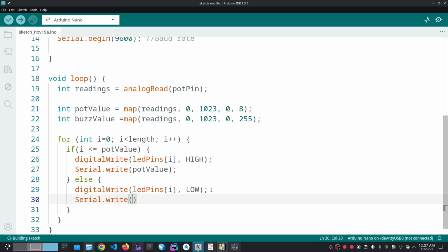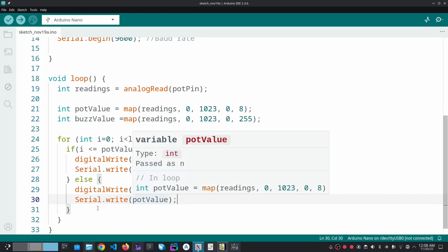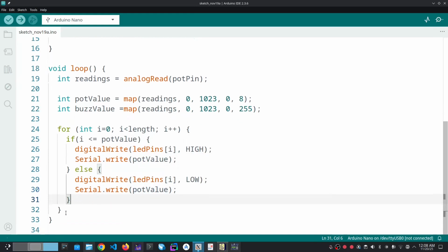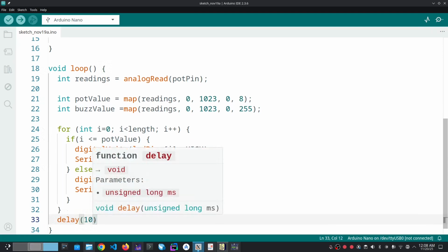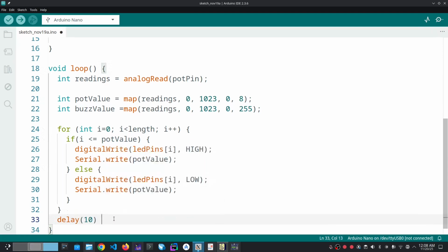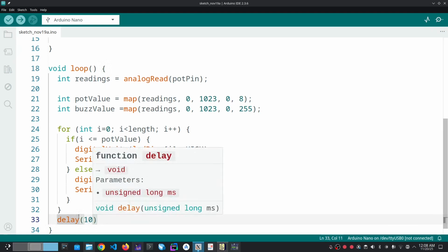That's right. That is our port value. Then, for smooth transition, let me delay for maybe 10 milliseconds here, in case of delay 10. If I put 1000, that'll be 1 second. So this is in milliseconds. So 10 milliseconds. So for 10 milliseconds, I will get what? I want that for smooth transition.